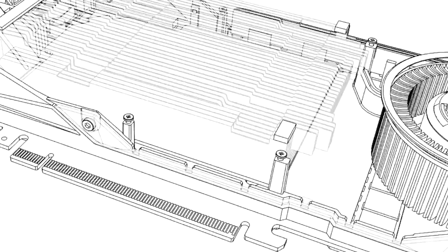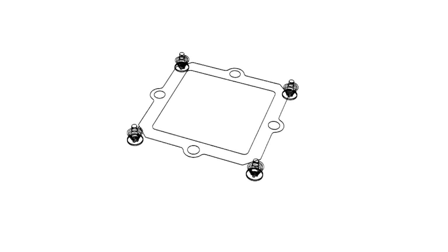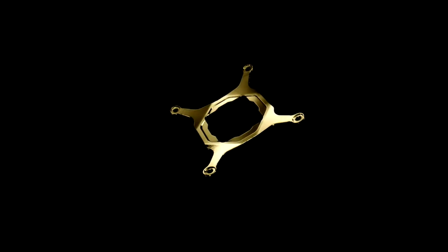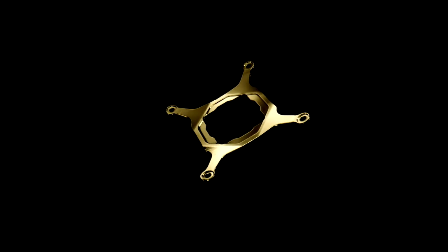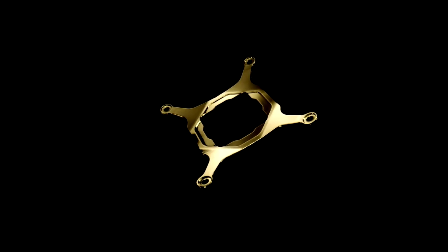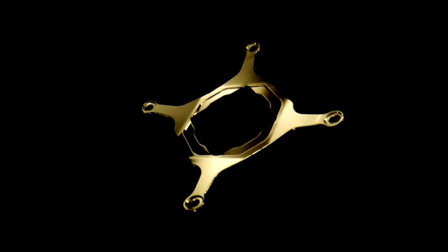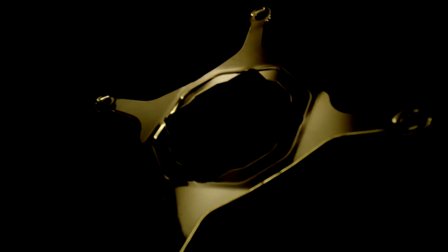The cooling solution is held to the PCB by springs. These springs historically are very tall, so we challenged our mechanical engineers to come up with a leaf spring design to keep the springs that hold the thermal solution to the GPU low profile enough that we could fit a back cover over them.